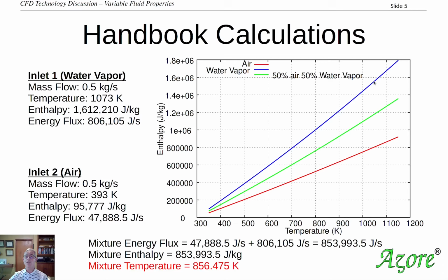So now we have this nice curve here, and we can use that to calculate what an energy balance representative temperature would be. We would take this number, go up to our graph, look at our enthalpy level, and just like you would look up in a steam table, you would go over and look right on the green line where this intersects, and then go down.